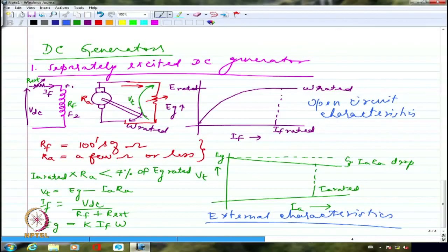Now a small twist I have to introduce in the external characteristics. All along we are assuming that the flux is unaffected by any armature current that is drawn. But the armature current is not going to keep quiet. It will also establish its own flux. Because of it, the main flux created by the field will get modified, whether I like it or not. As long as the armature was open circuited, the main flux was hale and healthy. But the moment I connect the load, the armature starts carrying current, and it is definitely going to throw its own spanner into the works.